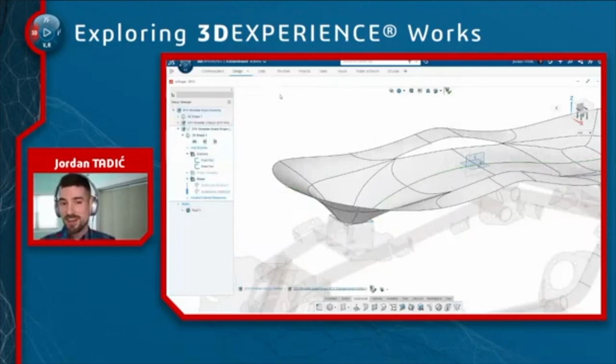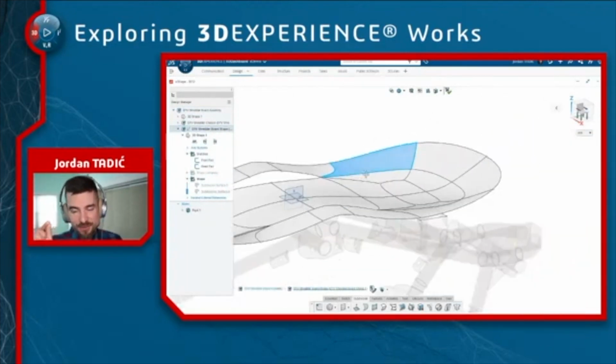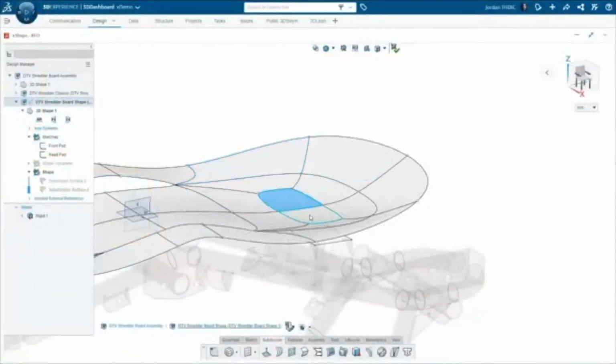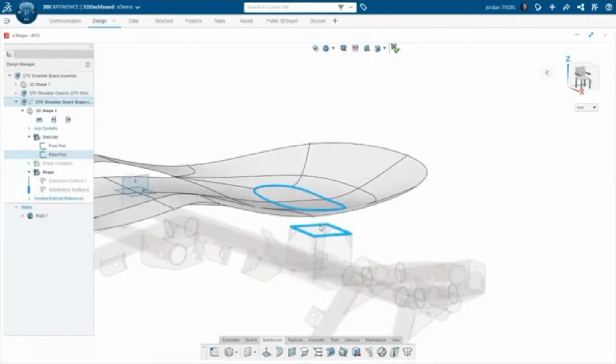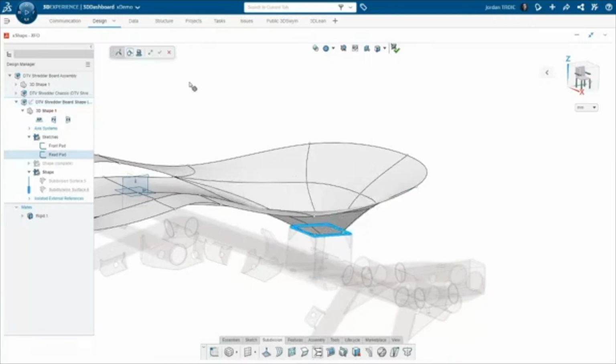It actually does. If I added fillets to that sketch, then I'd only have to select one edge of the sketch on the bottom. I should have done that to speed up this demonstration. I didn't even realize it at the time, because there's a tangent propagation checkbox in this alignment tool that would automatically loop around and select all the edges of that sketch.